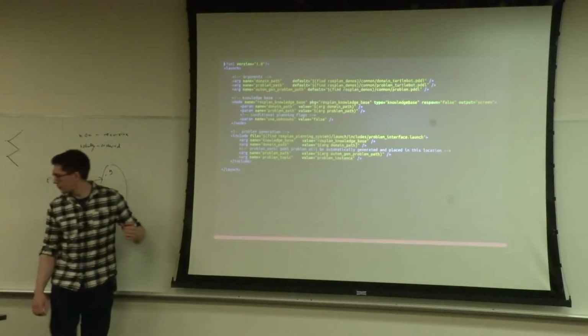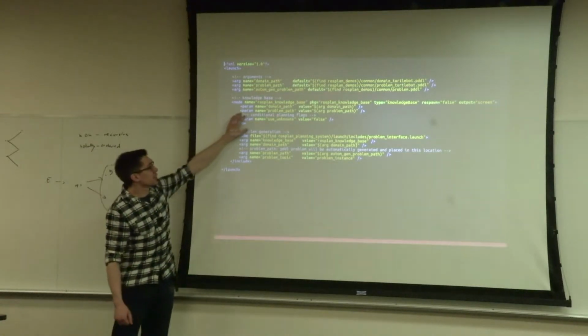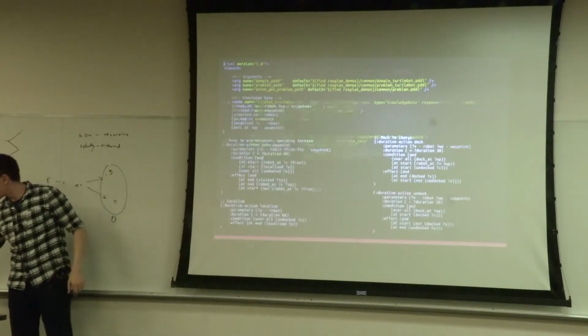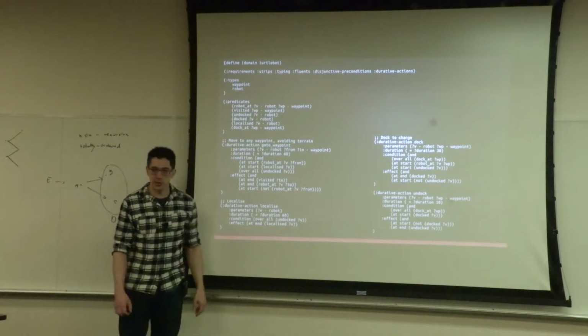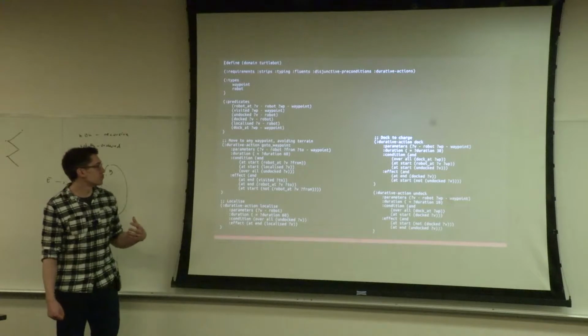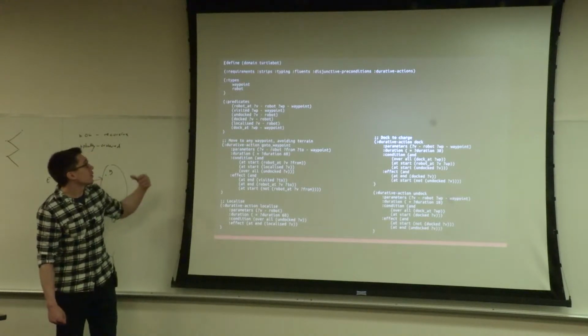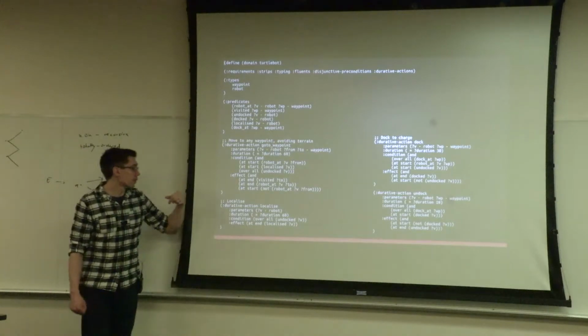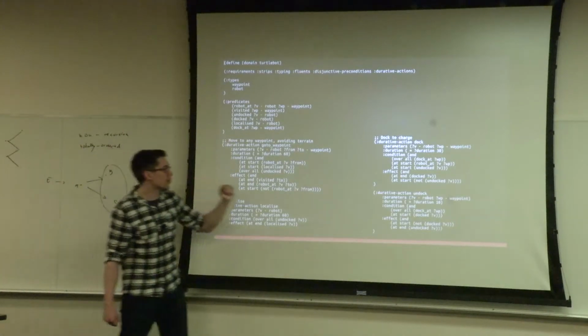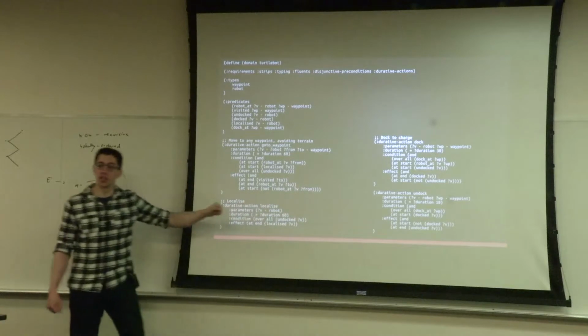Okay. The parameters on the knowledge base here are going to load a domain that looks a bit like this. This is our simple Turtlebot demo domain. We have two types. There are waypoints, there's a robot. There are 4 actions. The robot can dock and undock from its recharging station.